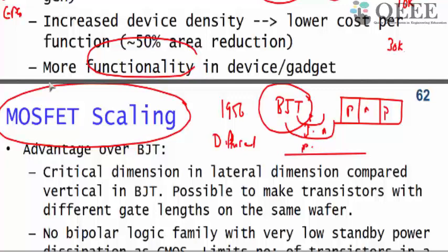It's very complex and a very expensive process if you want to try that. If you do one diffusion, you may be able to do the first diffusion. Then you mask that and do another diffusion in the other area. Because diffusion is a thermally assisted phenomenon, the second diffusion may affect your first transistor.